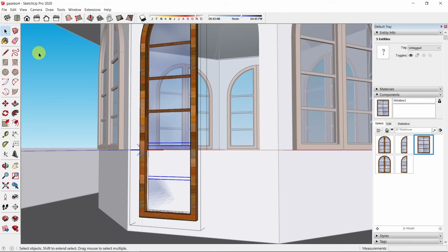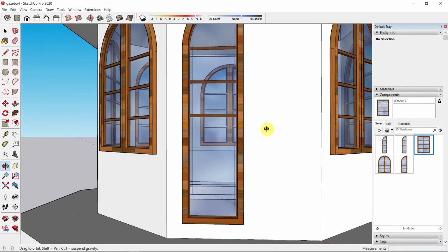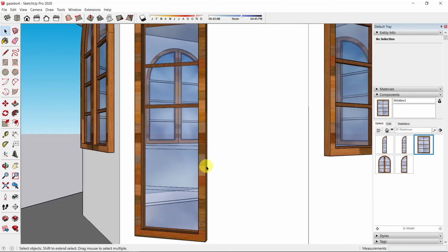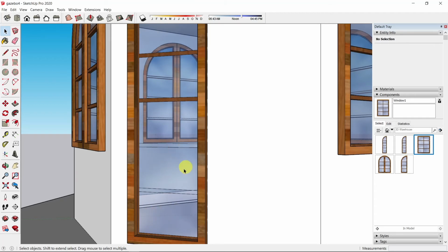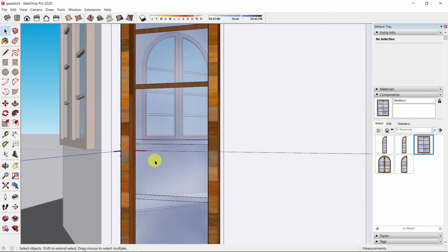So if I use the select tool to select anywhere outside my component, that exits the edit mode of the door half component, and then I click again to exit the editing mode of the door. So you will see, okay, this automatically cut a hole on the wall so you can see through. But I still need to finish the editing, so I need to double click once and double click twice.